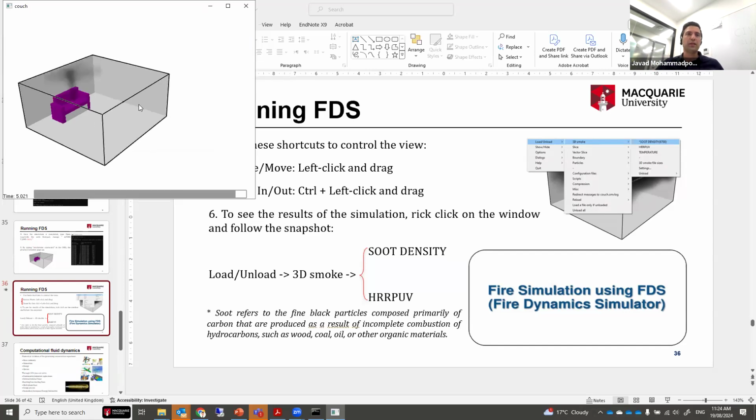Now you can see the soot here. If we extend the flow time, definitely you can see that this black cloud or the soot particles will spread all around and across the room. Just due to the limitation of our session time, I reduced that to 5.3.